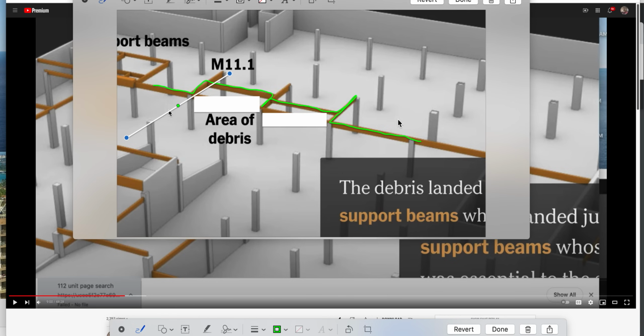So that means this structure here is the structure that initially collapses, the roof plane. I showed just now in the video that L is the one that everything's leaning towards. So L is the failing column that causes the buckling of all the floors that come towards that direction. This again is the load path of the structure. This is why it's two different structures.